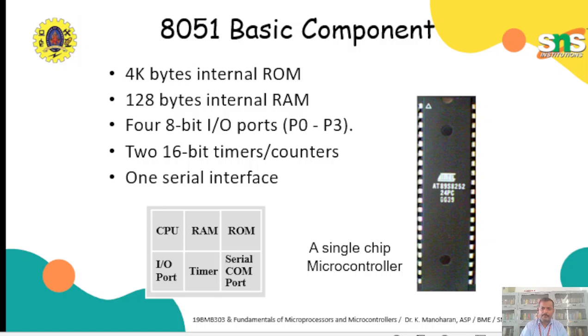Once it is configured as a hardware timer, it acts as a timer, and meantime the processor can do some other task. It counts internal pulses, and after a certain time it gives the timeout. So automatically it generates that particular time. This will be used to turn on or turn off lights or switches. The counter is used to count external pulses. For example, how many people are entering our classroom and how many people are leaving.